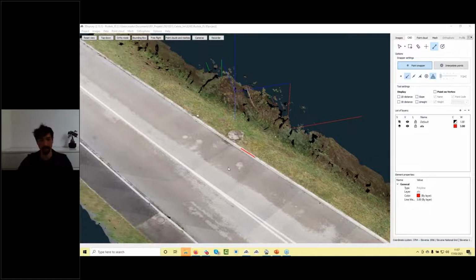Okay, just once again, support us with the elevation coordinate system. So this is the geoid model. Support us with the geoid model, which you have in your GPS system. If you don't know where it is, the easiest way is to ask the person who sent you the GNSS instrument how you can get this geoid out of the instrument and send it to us. We'll transform it to the 3D Survey file format, send it back to you and give you the instructions on how to install it. It's actually pretty simple.